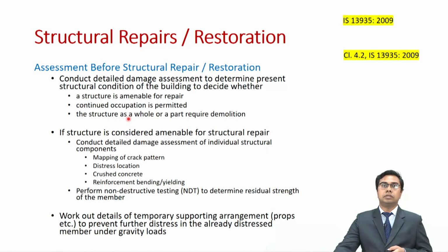If a part of a structure or the whole structure requires demolition, that is, the reconstruction cost is comparable to the retrofitting or restoration cost, then in that case we may have to demolish the building as such. So, if the building is considered amenable for structural repair, we will conduct a detailed damage assessment of individual structural components now. Earlier we have done the detailed damage assessment of the entire building, but once the building is considered to be suitable for structural repair, we will do the detailed damage assessment of individual structural components, in which